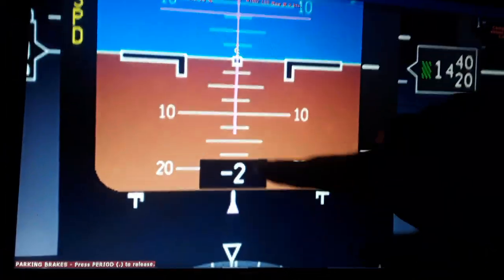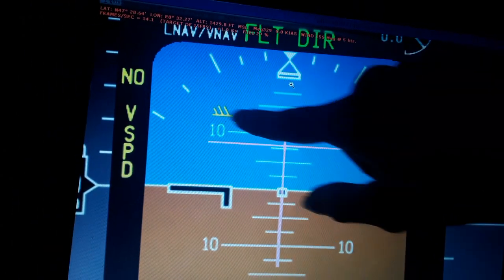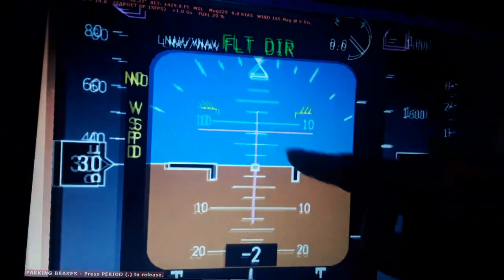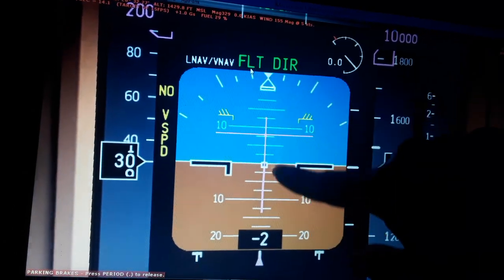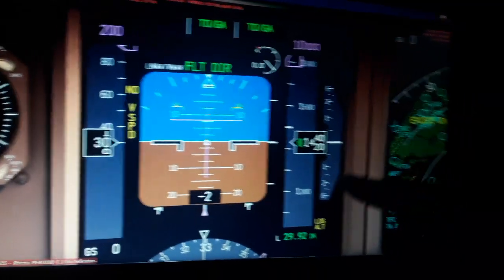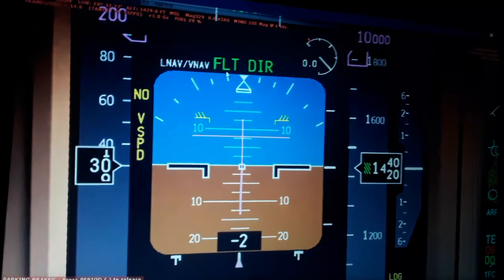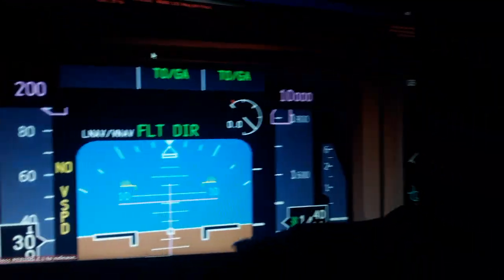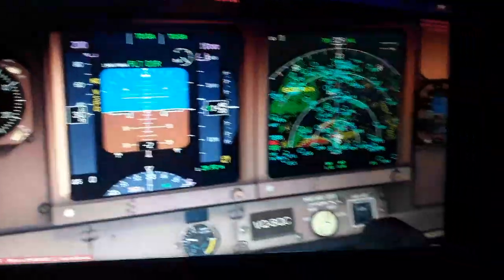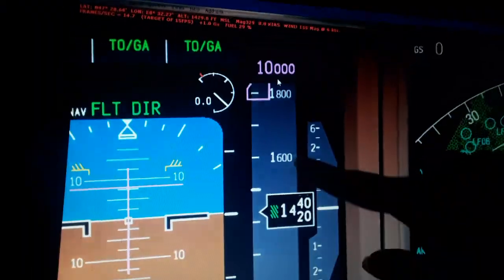You can see the pitch ladder 2.5 degrees tick marks, 2.5, 5, 7.5. So this is the pitch attitude 10, 12.5, 15, 17.5, 20 of positive pitch attitude or negative. So you can see also the vertical rate of climb in the center of the aircraft over here. We have the bank angle also limited degrees, the angle of attack of the aircraft as it flies in the flight mode and consider the autopilot of the throttle, the down vertical navigation modes. These displays how fast the aircraft climbs and descends.